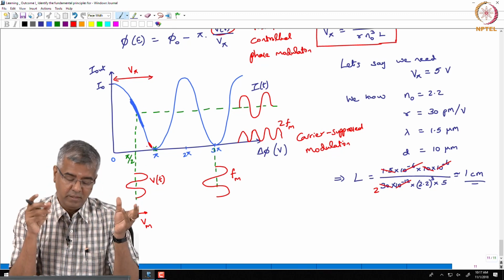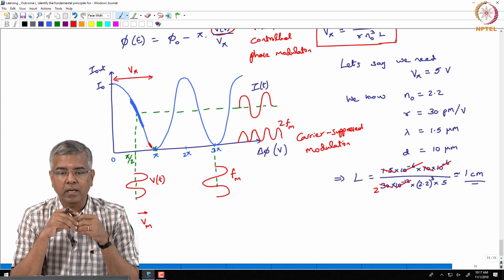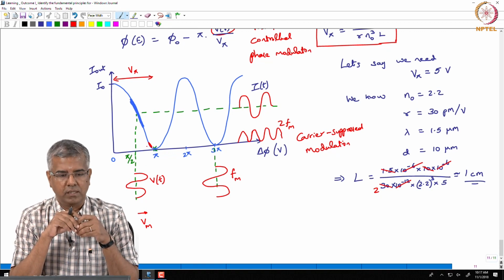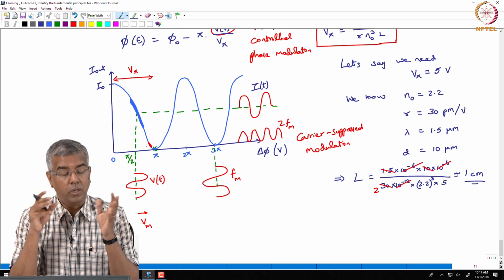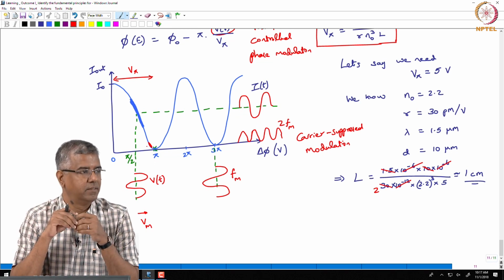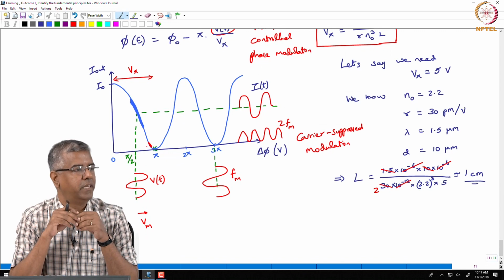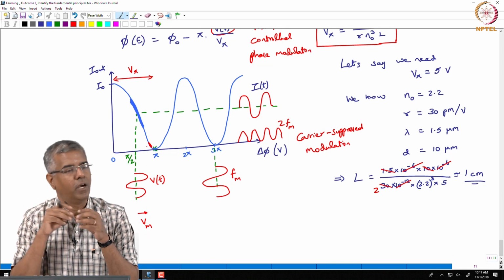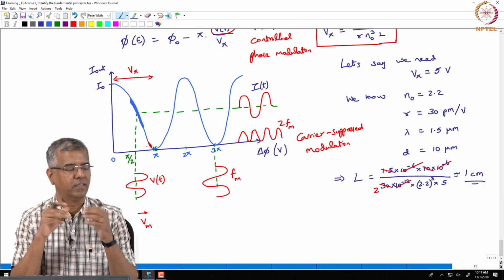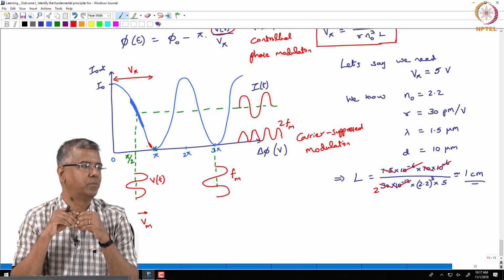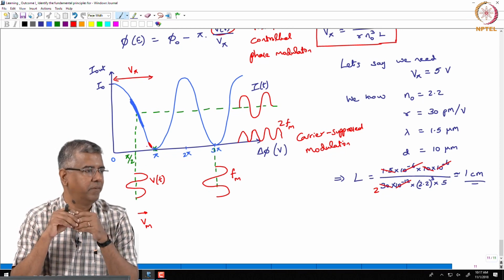In a certain way, and this is very widely used in signal processing and power electronics, you look at the harmonic content and you can tell whether you have a linear response or not. If you have a large harmonic content, you say the response of whatever system you are analyzing is not behaving linearly.